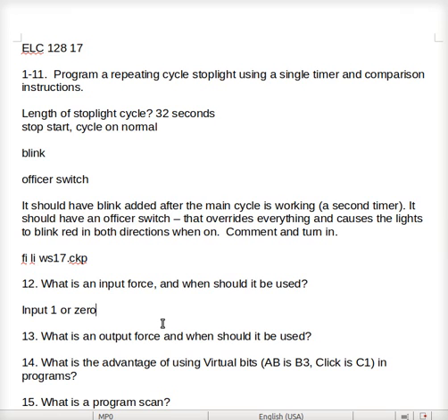Because what you're basically doing is, let's say my start button doesn't work, so I'm going to force it. If it's a momentary, I would think that would be okay. But if a stop button's broken and you're forcing it to be a 1, you have to be careful, because you could come up with a scenario where you can't shut the machine off with an input force, and that would be bad from a safety standpoint for sure. Okay, so that's your input forces. Once they're applied, when the PLC scans through the logic, it will use your input forces as part of the logic and determine your outputs.